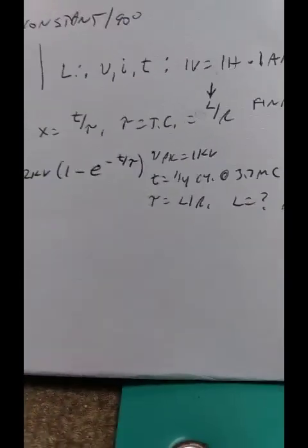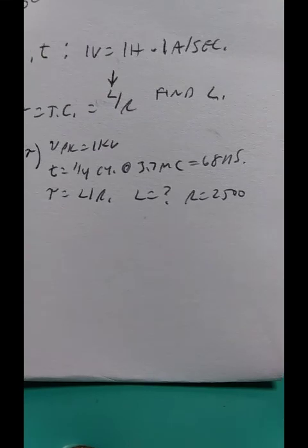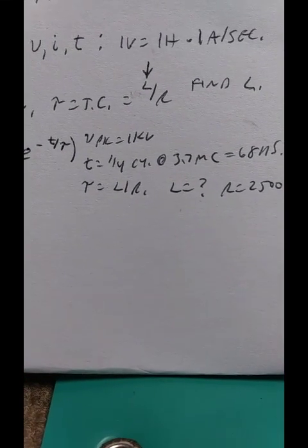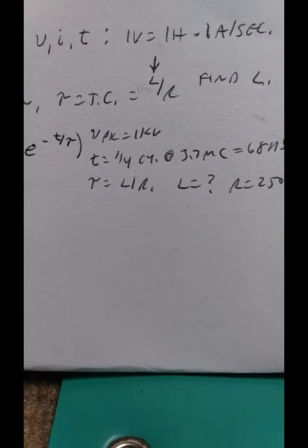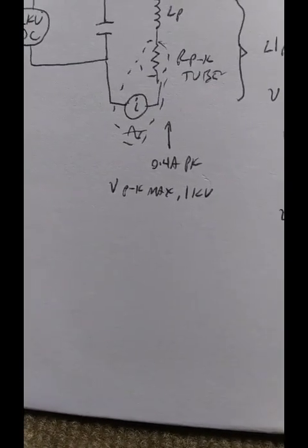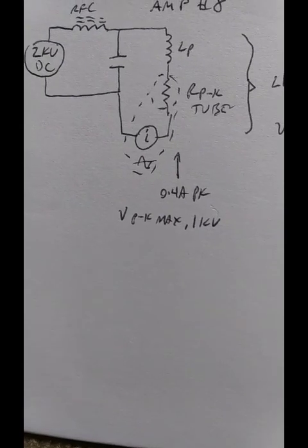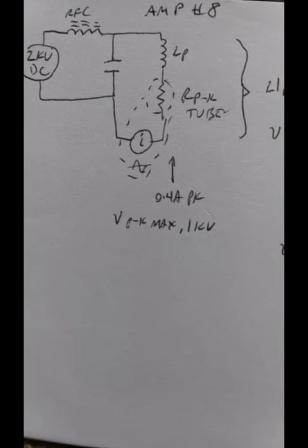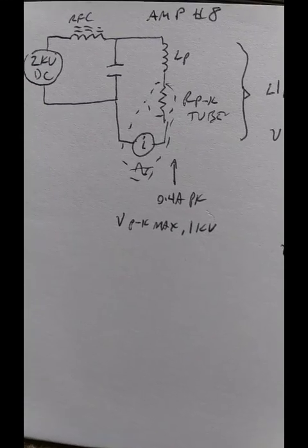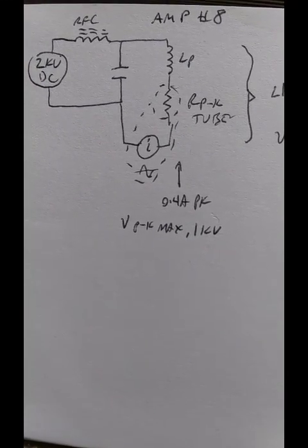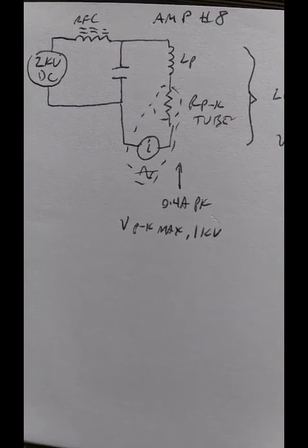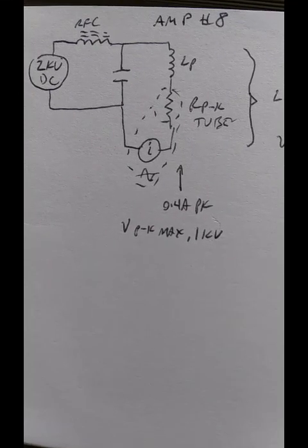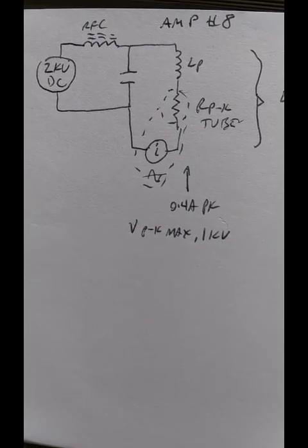For this amplifier, for my assumptions of 1 kV, 4/10 of an amp, and so on and so forth, the inductance becomes 245 microhenry. And that's a fairly high value for a typical RF amp, where it might be 100. Well, I'm very, very underloading this amp. 1 kV at 4/10 of an amp peak may not even be half what a 3-400 is capable of. But again, I don't care about running full power. I'll be glad to get 800 watts. That'll really help. And initially building the circuit where the tube's only dissipating half or a third means that we can afford to make a few mistakes and not destroy the tube.